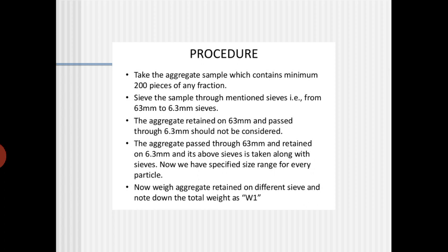Aggregates greater than 63 mm size will be used for the sub base in designing the roads. Normally these aggregates greater than 63 mm are used wherever strengthening of the subbase layers in the roads is required, when they are designing the roads.